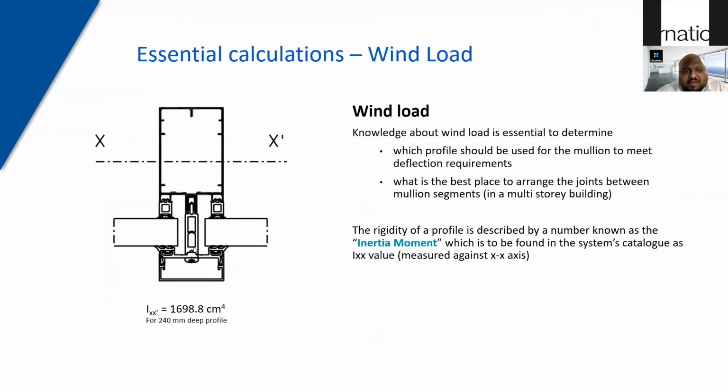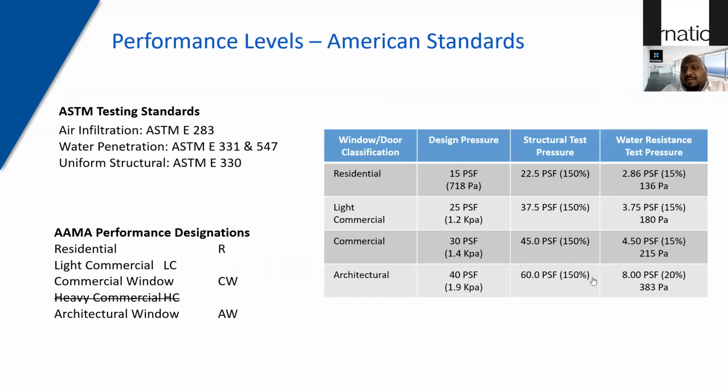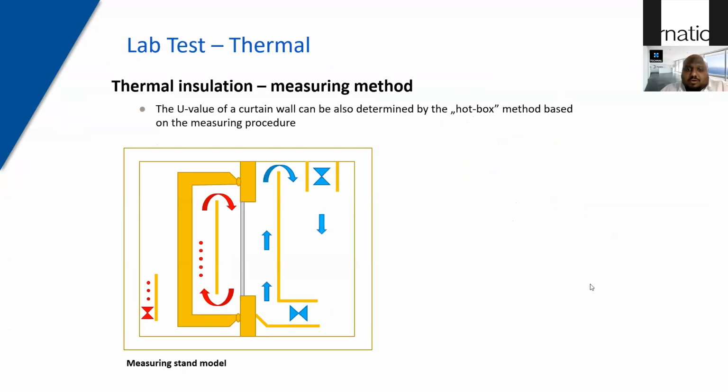By using this thermally broken profile, which comes as default for all of our curtain wall systems, you reduce cooling loads, and we have data to prove that on a hot day you save 20 to 30% of energy bills by simply using thermally broken curtain wall. So this is how we break that thermal bridge from out to in, by using polyamide. The same applies to a window or a door system.